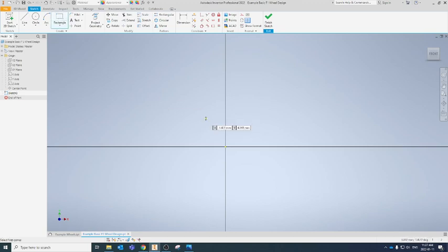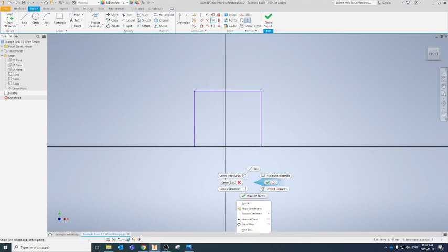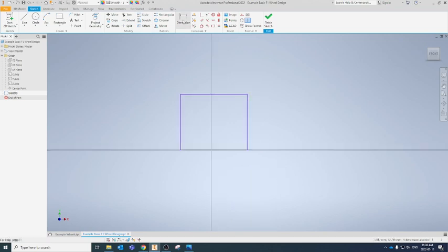I'm going to start by just designing a 2-point rectangle. I'm going to line up the bottom of my rectangle by using my horizontal constraint on a bottom corner onto my origin point. That just lines up the bottom of my rectangle with my origin. And then we're going to throw a couple dimensions on. I'm actually just going to throw these on and then change the numbers in a minute. I'll throw this one on, we'll start with that, throw this one on and we'll go change this.